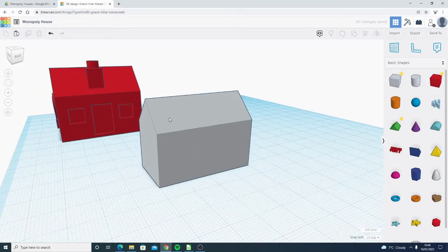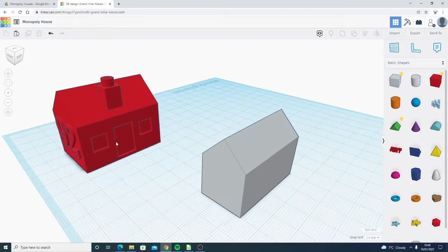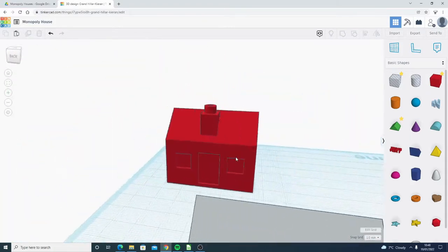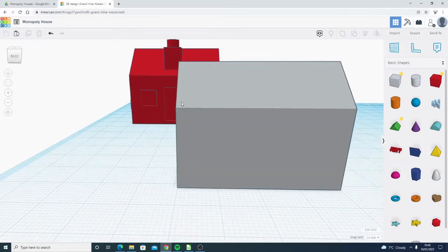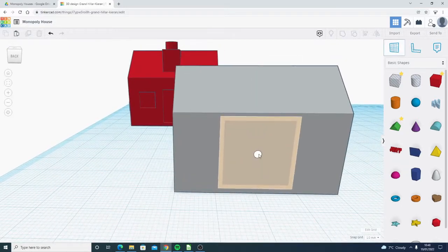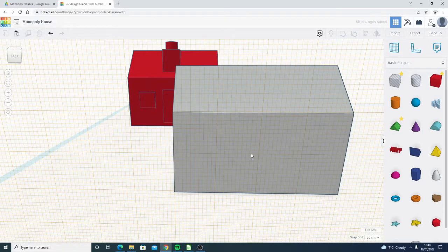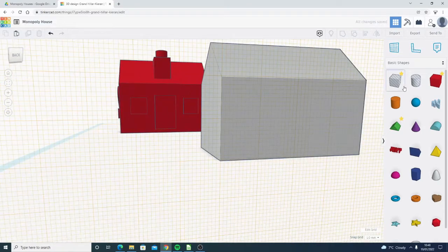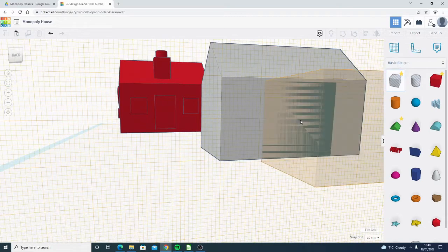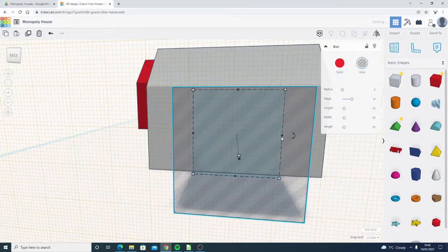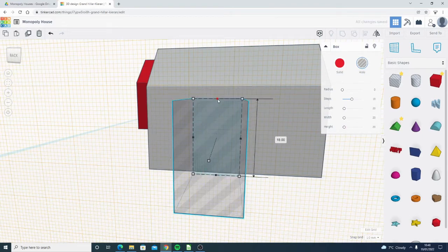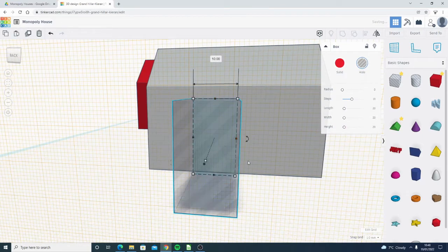We're now going to put in a couple of indentations for the doors and the windows. So this is how you do that. You take your work plane and you place it on the surface that you want to work on. Hence why it's called a work plane. So I'm going to click on the box tool and just position that and make a door. Now notice it's glitching. That's telling us that this shape, this hole, is directly on the surface.